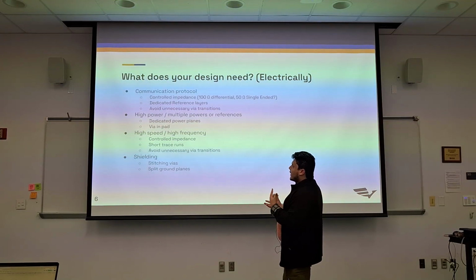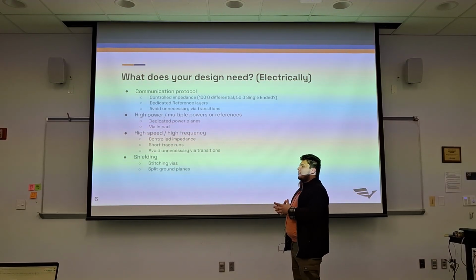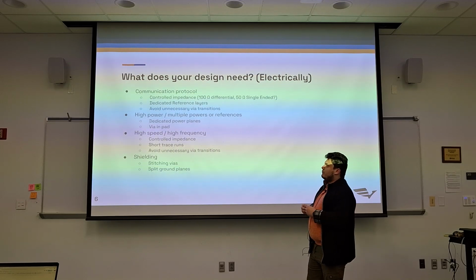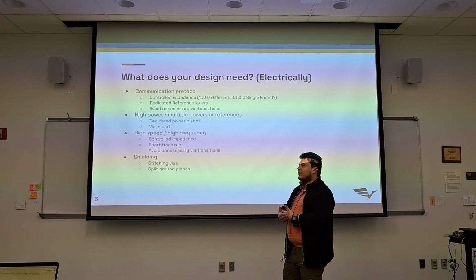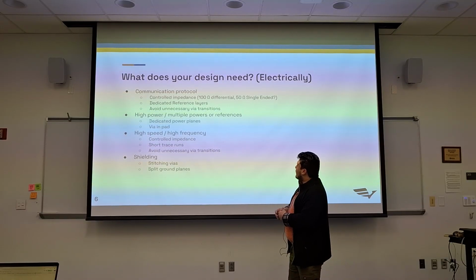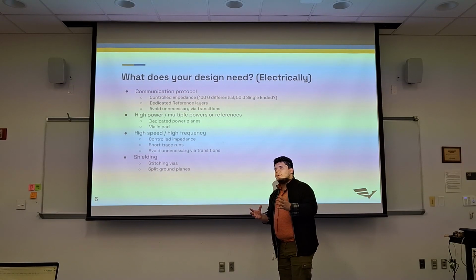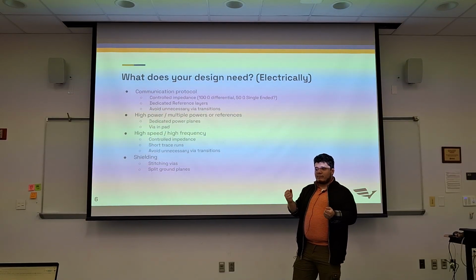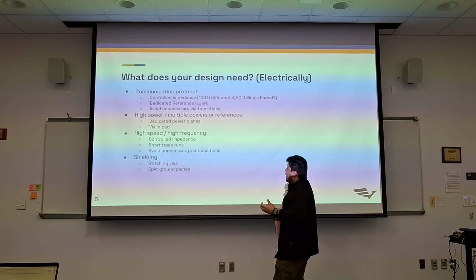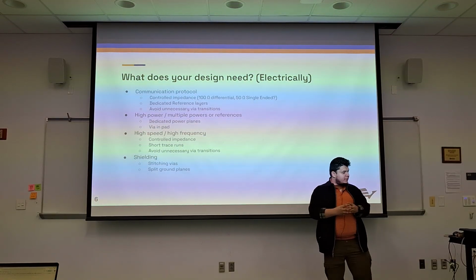Are we going to have anything high frequency? I think the highest frequency that we have is 50 kilohertz, which is, in the grand scheme of things, not that fast. But we still want to pay close attention and treat those like they're a baby, right? We want to put a lot of attention on that. And are we going to need shielding? Is this board going to be in a very noisy environment? Are there a lot of magnetics going on? How much shielding do we need to protect our components?